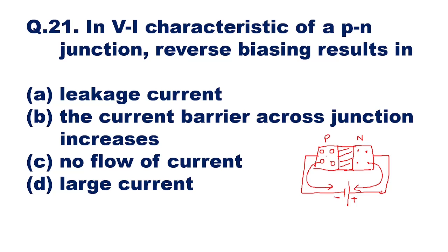In p-type semiconductor there are a few electrons which arise because of rise in temperature, and because of that the covalent bond breaks, and so we get a few electrons. Similarly, in n-type semiconductor, we get a few holes which are called minority charge carriers. These minority charge carriers are there because of rise in temperature, which causes some covalent bond breaking, and because of that these electrons and holes come into picture.